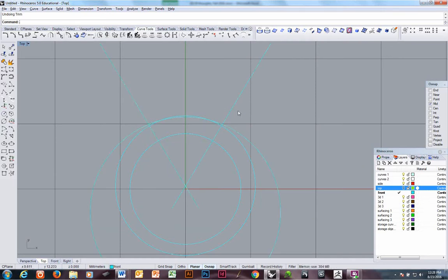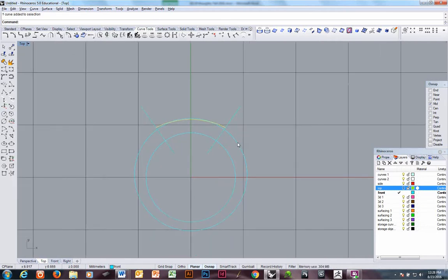Until that trim was gone. I would delete these two curves. And then I would paste, Control V. It would bring them back, and then use those to trim. That way I know it's still my original circle and everything stayed tidy. That's just hygiene. It's just what I would normally do so that I'm assured that it's working well.